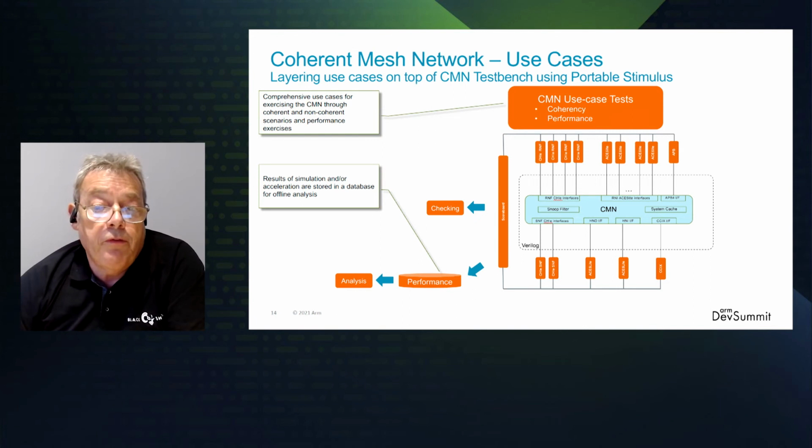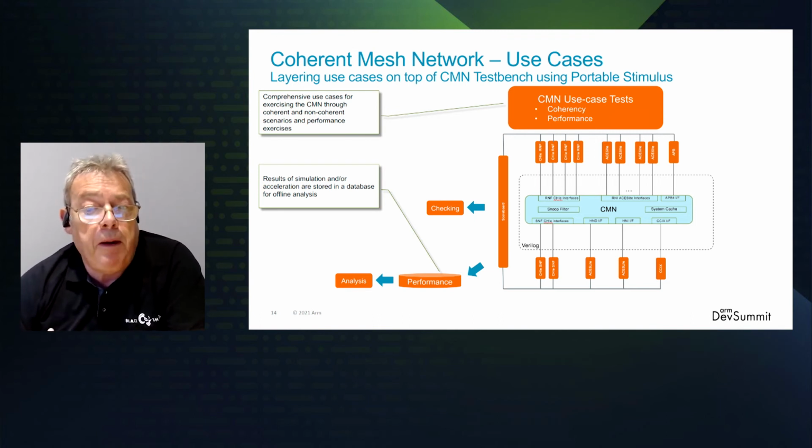which provides a method for modeling system behavior and dependencies in an abstract way, which can then be used by tools such as Cadence Perspec to generate a fully formed scenario from the abstract use case model, and uses a constraint solver. By providing libraries of content for specific challenges such as coherency, performance modeling, and PCI Express, the users get a powerful jump start to create complex content right out of the box.